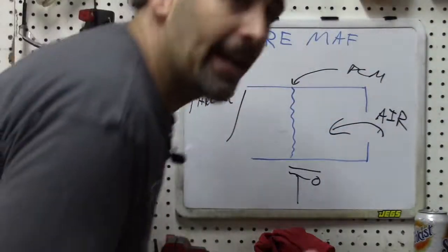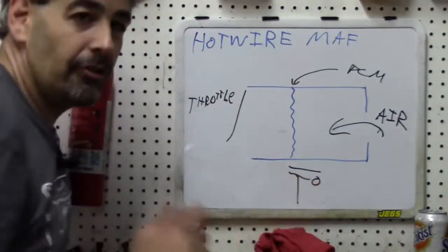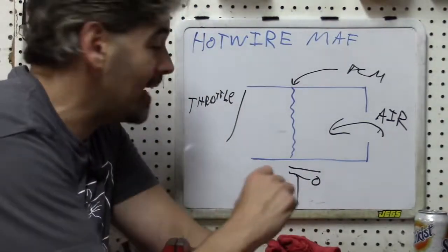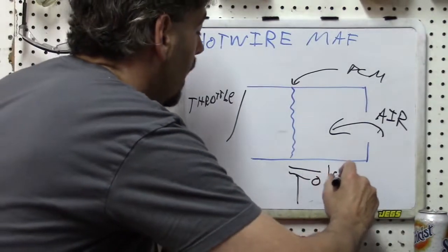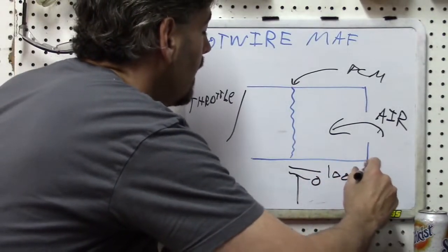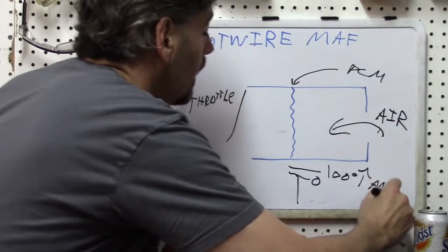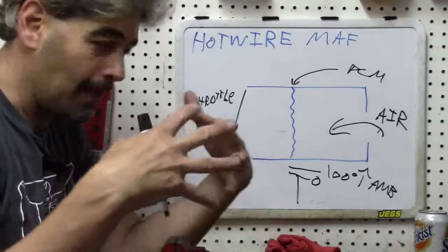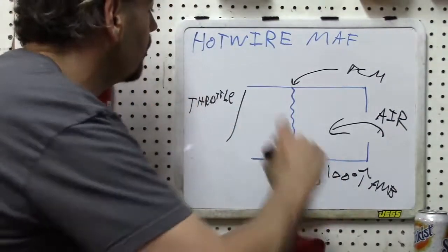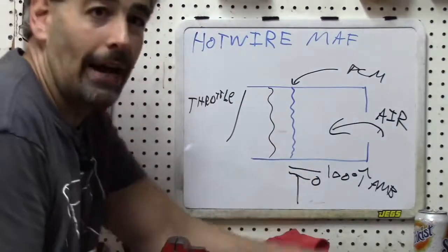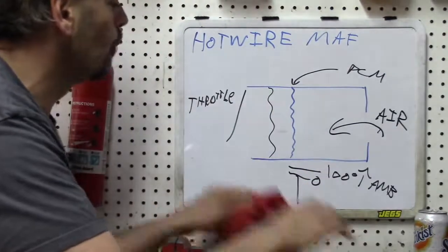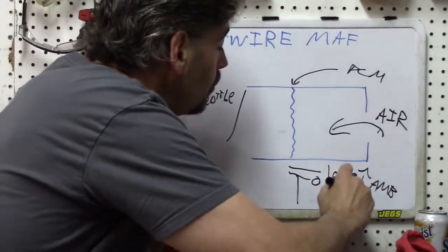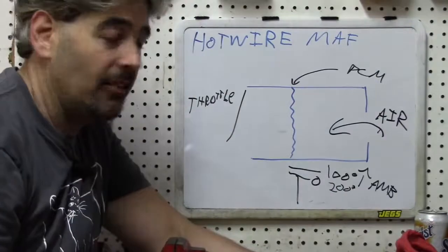Different service manuals have said that this temperature is vastly different things. The GM service manual there, I believe, said that it was 100 degrees above ambient temp. How would it know the ambient temp, by the way? Intake air temperature sensor coming together. Some sensors also have another wire here called a cold wire used to make a comparison as well. But other references that I saw said that it was as high as 200 degrees over ambient temperature.